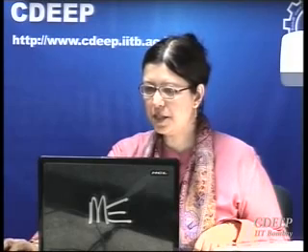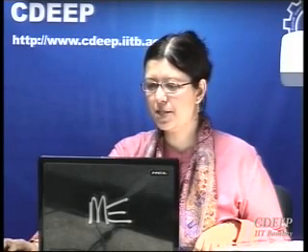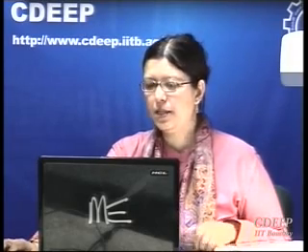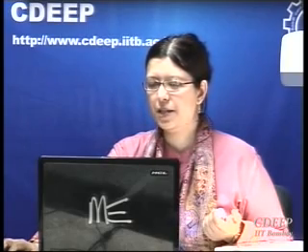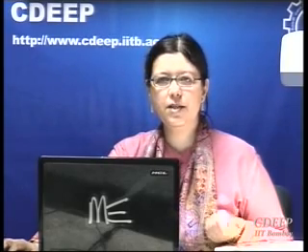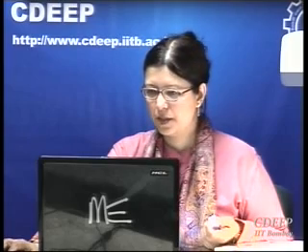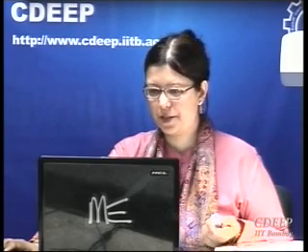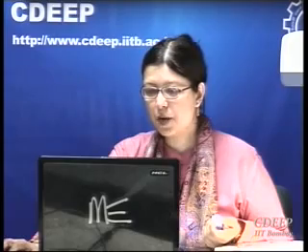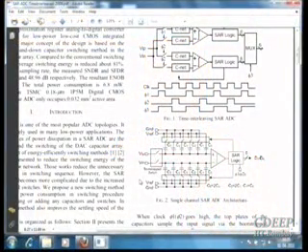The remaining part is very straightforward. The only difference is that it's a differential architecture. In the class, we covered single-ended architecture. So it is just interleaving. Then there is a black box here, which is called a bootstrap switch. Bootstrap switching is not explained here. Again, bonus for group 2. You are not forced to use this switching. You can use simple switching, but if you do it, then you will get a bonus.